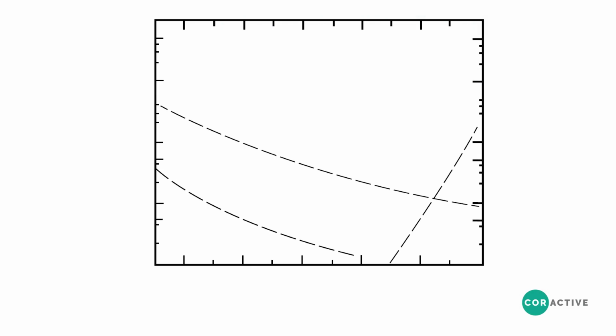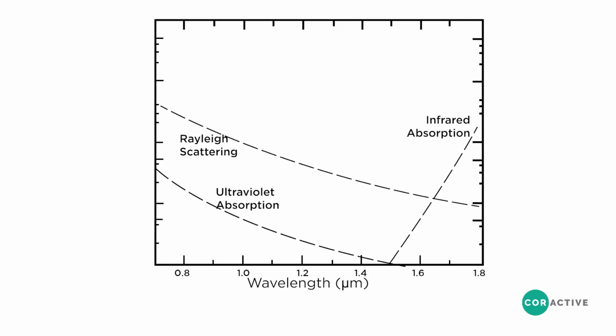Even in a perfect situation, the glass material has intrinsic loss components. The phenomenon of Rayleigh scattering has a major contribution, where the particles in the fiber material itself scatter the light. This limit is there even in perfect glass, and with impurities, it will increase. Fun fact, this is the same phenomenon that makes the sky blue.